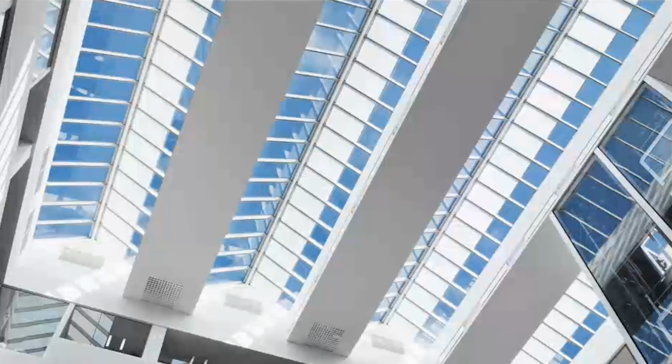Interior blinds. Interior blinds are primarily used for glare, and I'm going to talk about glare later, but with regards to solar heat gain, they do reduce your solar heat gain by 30 or 40%, depending on the blind, depending on the application, or on the product, but they can reduce the solar heat gain. And they do that in part because the heat's already getting through the glass, but you're heating up the blind material. Some of that heat is radiating back through the glass, and some of that heat is radiating into the space below. So it's not optimal, but it does reduce it.